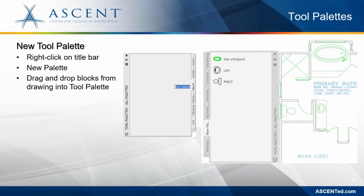Name it as per your requirement, and once the custom palette has been created, it is obviously empty to begin with. So here you are required to add the blocks to it. For that, you need to have your drawing open where these blocks have been saved. Now simply drag and drop the blocks from the drawing onto the palette space to create tools for those blocks.